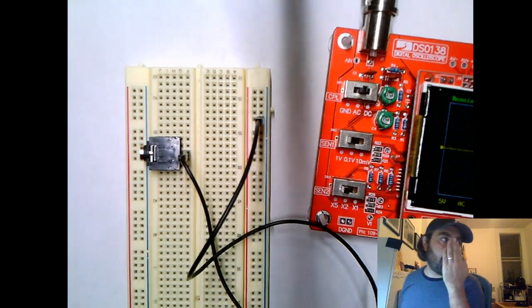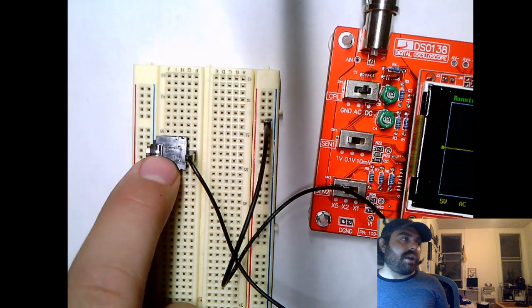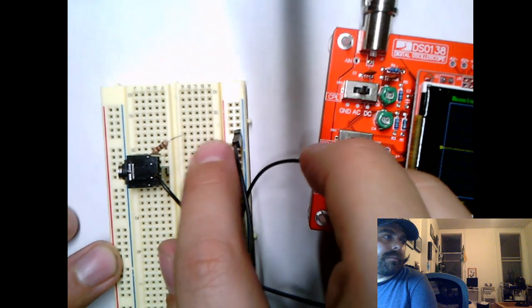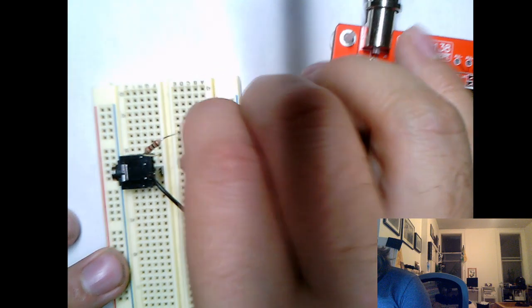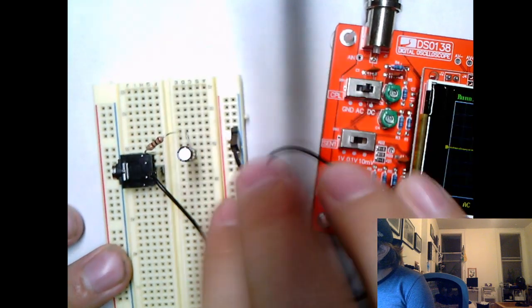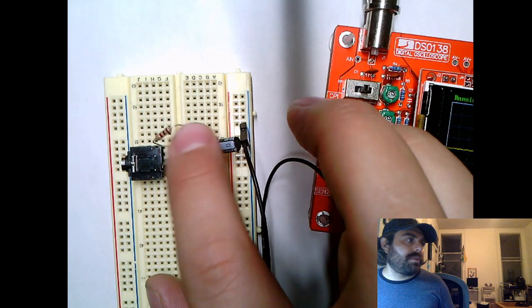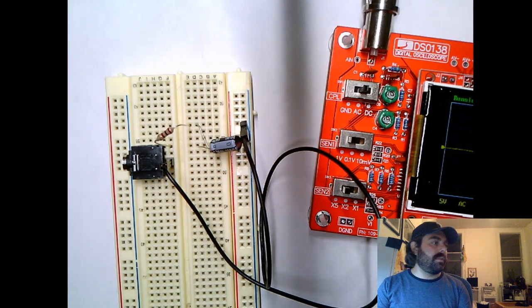Remember, no batteries this week, but I need my reference for my audio signal to be the same reference as my circuit. So grounds need to be connected together. Okay? Then I'm going to take this resistor and I'm going to come out of the top pin and just go into a random row up here. And then I'm going to take the positive leg of my capacitor and meet that and just pick another random row. Okay? So I've got the long leg meeting the 100 ohm resistor here, and now my short leg is here. And we'll go back and kind of look at this.